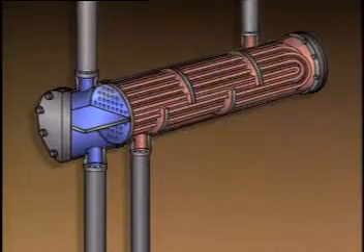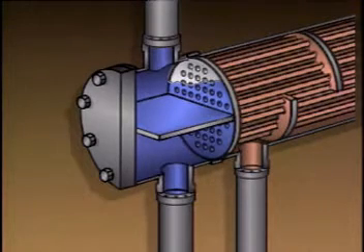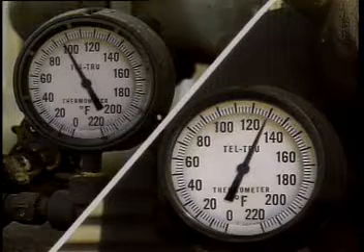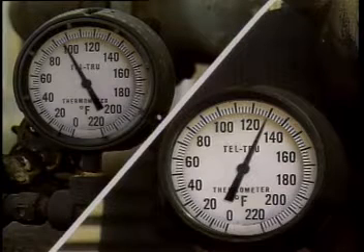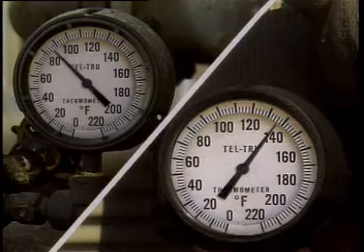For example, when trapped gas blocks flow to some of the tubes, the outlet temperatures of the two fluids may change. This is because the gas is restricting flow into the tubes, and the restricted flow causes less heat transfer surface area to be available. The decrease in heat transfer surface area will cause the outlet temperature of the process fluid to increase, since less heat will be removed from the fluid.